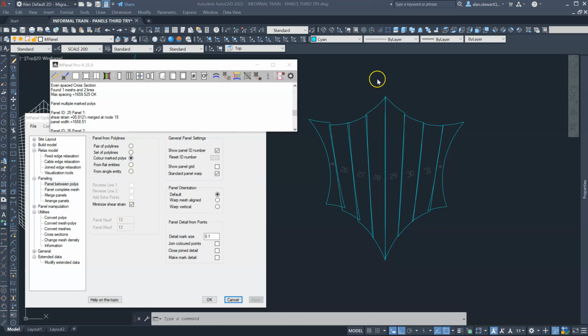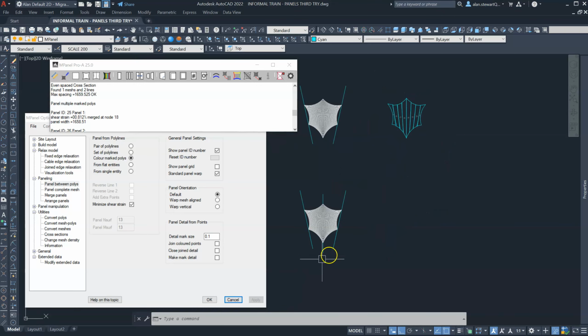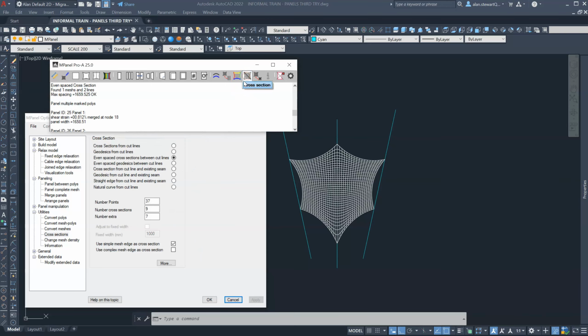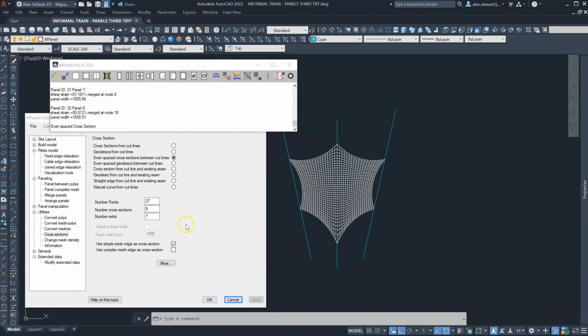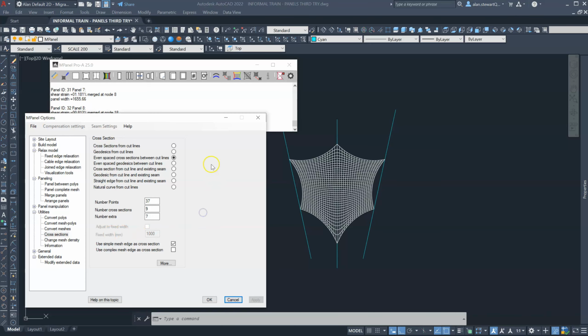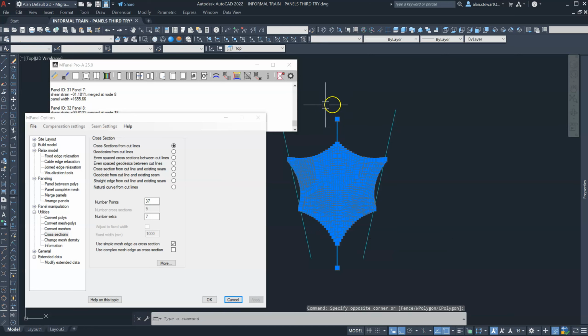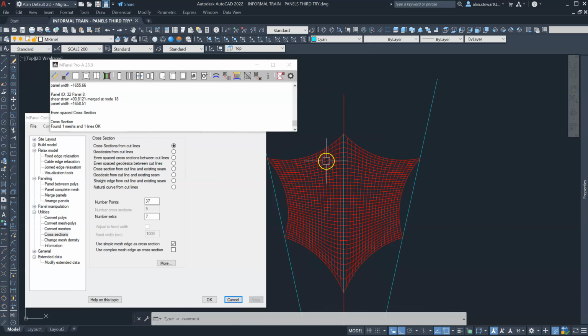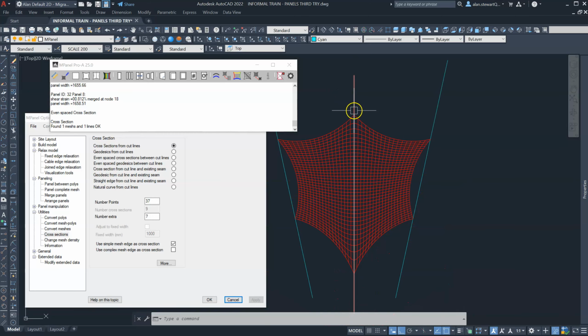fabric width. Now another way to do cross sections is to use some of the functions inside the cross section toolkit to actually specify the fabric width. Now in order to do that, the first thing we need to do is we're going to make a single cross section through the center, and you can see that now gives us a new cut line. We can delete the old.